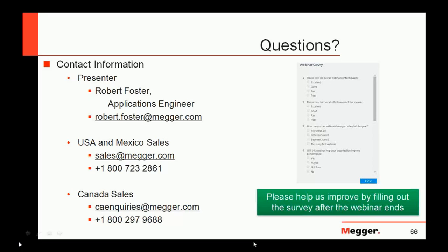Okay. Robert, Gary asked that many manufacturers claim that it is not necessary to test motion in a vacuum circuit breaker. In your experience, is this true? What I've seen with the vacuum circuit breaker is at the factory, they're measuring motion for sure, because a lot of times it's for that rebound parameter where the contacts touch and it backs off.